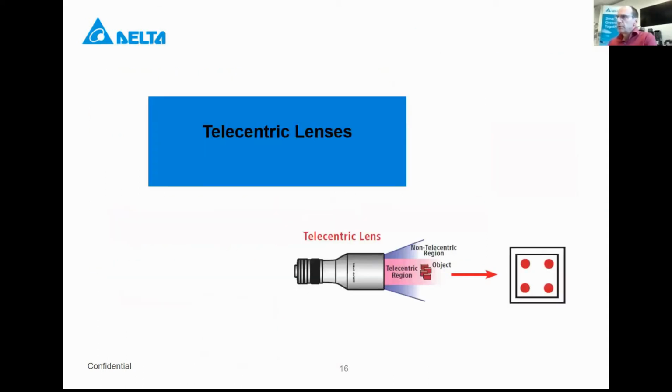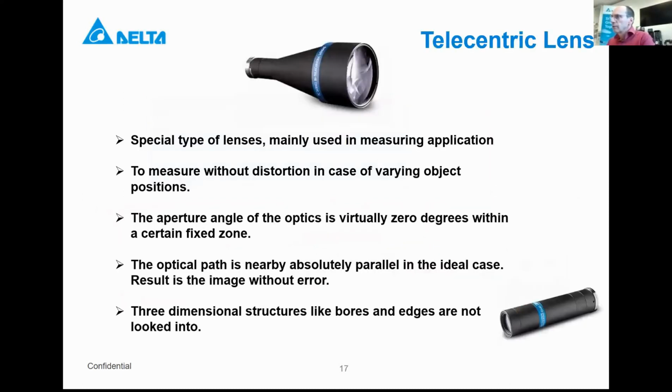The opposite is the telecentric lens. You see it already in the picture. Telecentric lenses are special lenses, and are also expensive. Depending on the lens itself, your working distance and the size of the lens are already decided, and your field of view is already fixed. You cannot change it anymore. That is chosen by choosing this lens.